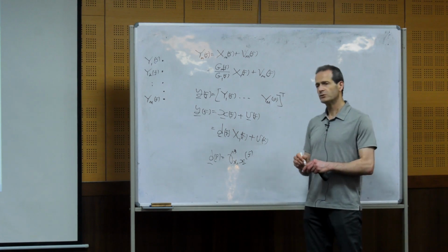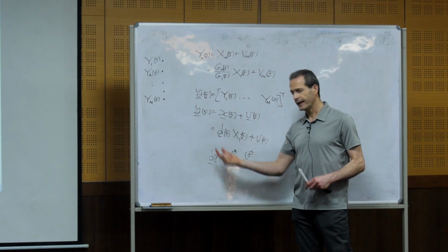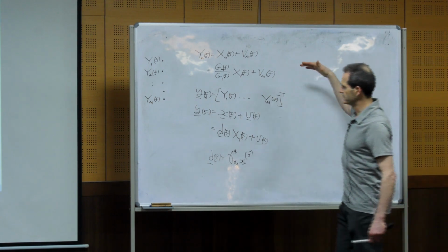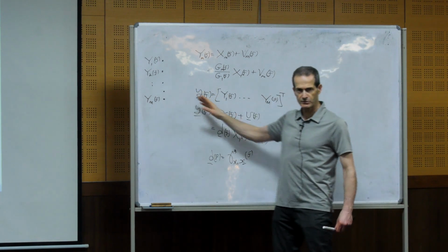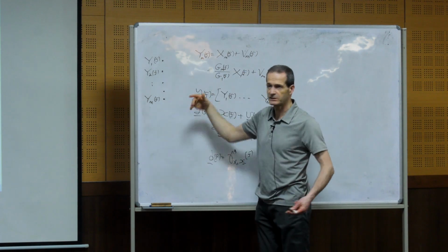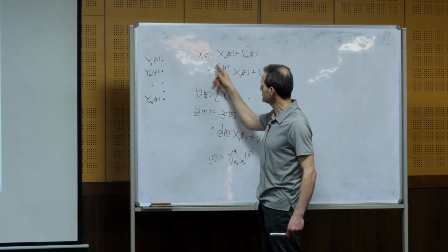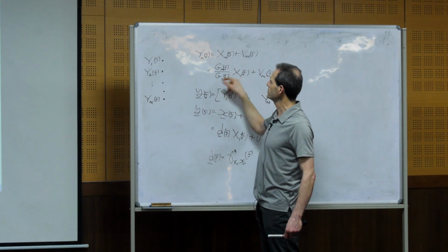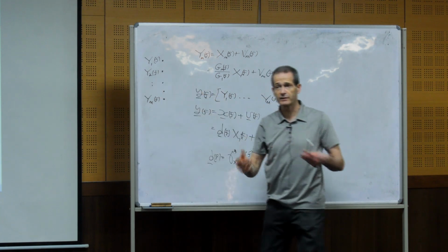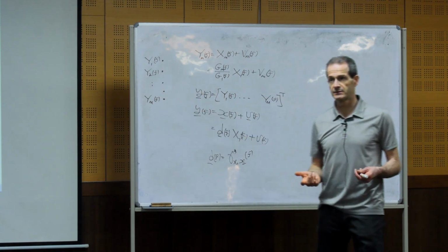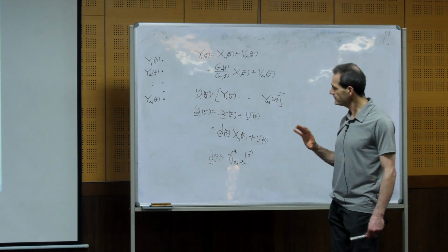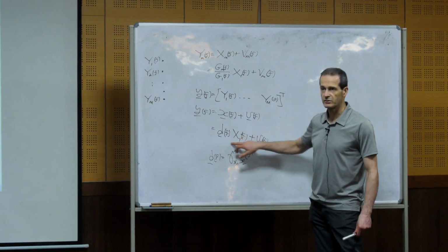But what you need to understand is that this contains a lot of information. First, where the desired source is, which direction it comes from. Also, reflections in the environment. If it includes reflections, they will be included in the transfer function or relative transfer function. And also, it depends on the configuration of the array, where you put the sensors in the environment. So all of that information, we use it in this vector.